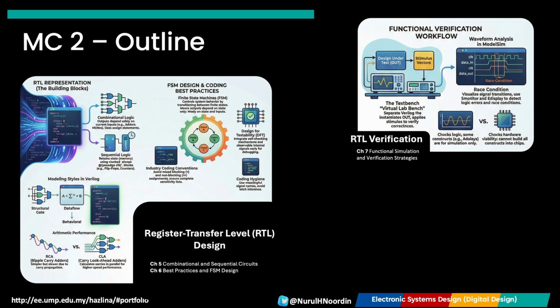But before we ever touch a physical chip, we must prove our design works. In chapter number 7, we dive into the functional verification workflow using tools like ModelSim. We will write test benches, apply virtual stimuli, and perform deep waveform analysis to hunt down logic bugs and validate our system in a safe, simulated environment.